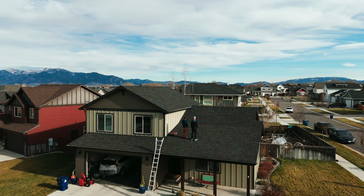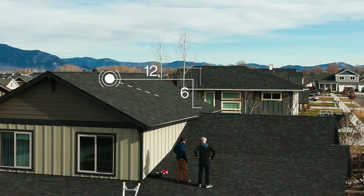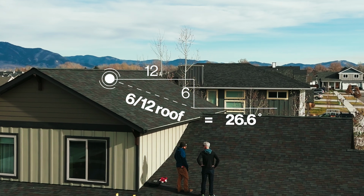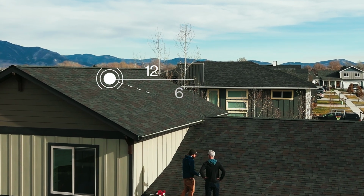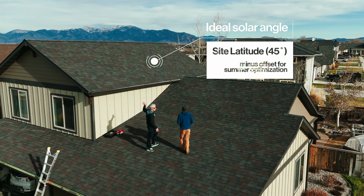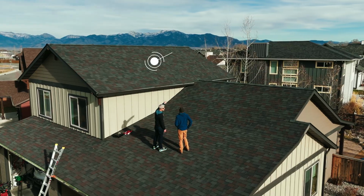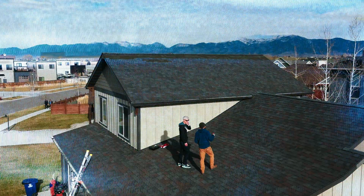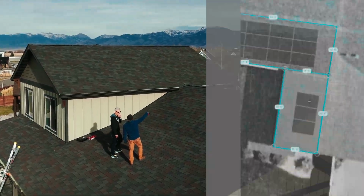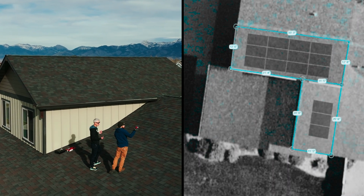An ideal roof pitch at this latitude is 33 degrees. Anywhere between 4/12 to 6/12 is pretty ideal for maximum production. The sun's up higher in the summer versus winter, so you actually want a little bit shallower pitch to maximize your summer production. That makes sense? We'll have a subarray of 3 on the east, and then we'll have the majority of the panels up top here on this beautiful south aspect.